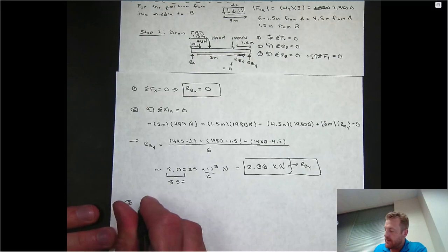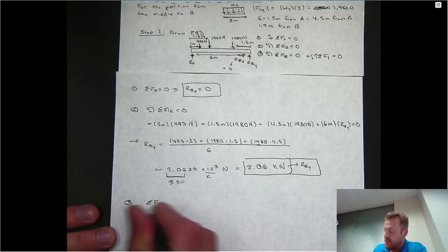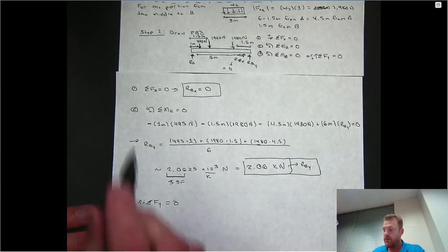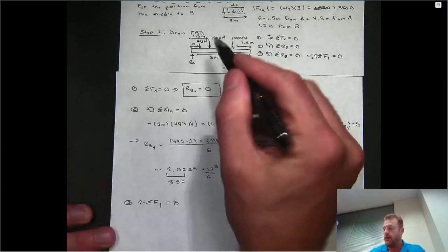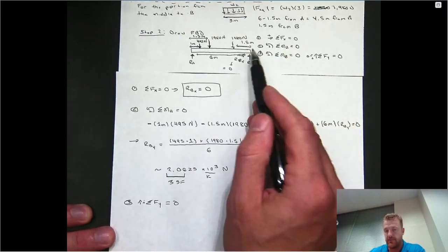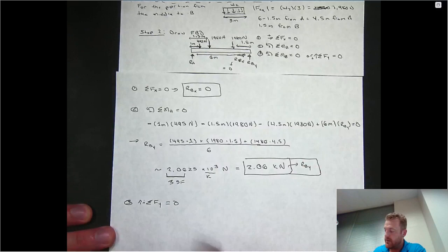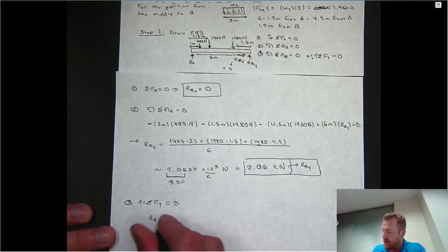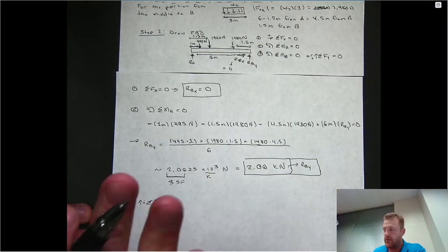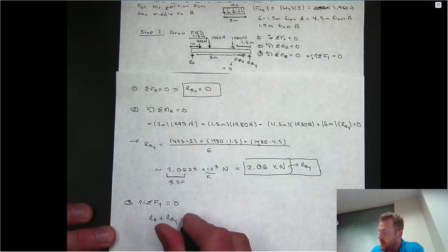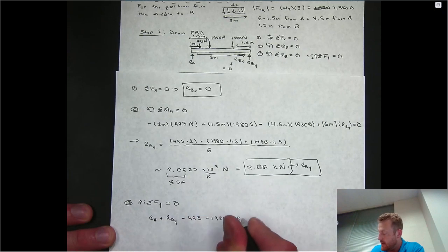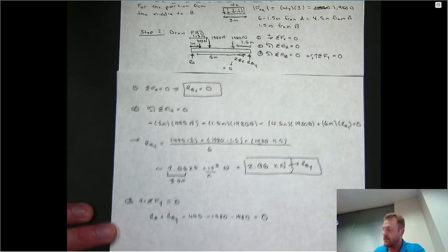I'm just going to do that to make this video a little bit shorter, since I know it's getting a little bit long-winded. All that this is going to show me is that all the applied forces, which go in the negative y direction, have to equal the sum of the two reactions, which go in the upward direction. So you can show this as RA and, keeping my notation consistent, RBY. Those are the two forces going upwards, and those have to oppose the 495 down and the 1980 down and the 1980 down. Those all sum to 0.